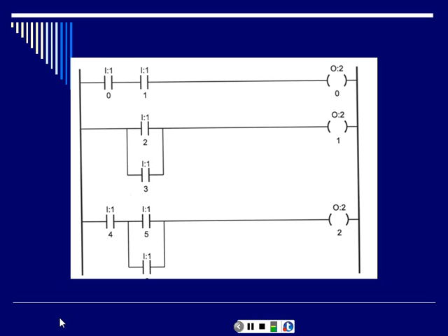Now, when you read from rung zero down, you start at the top, left to right. Yes, correct. So rung one or rung two can't be activated unless rung zero and one activate. No, sir, that's not true. Rung three can still be activated without. Yes, it can be. I can activate those independently. I could also set them up so that they were activated like you're talking about, where one wouldn't work without this one and this one and this one.